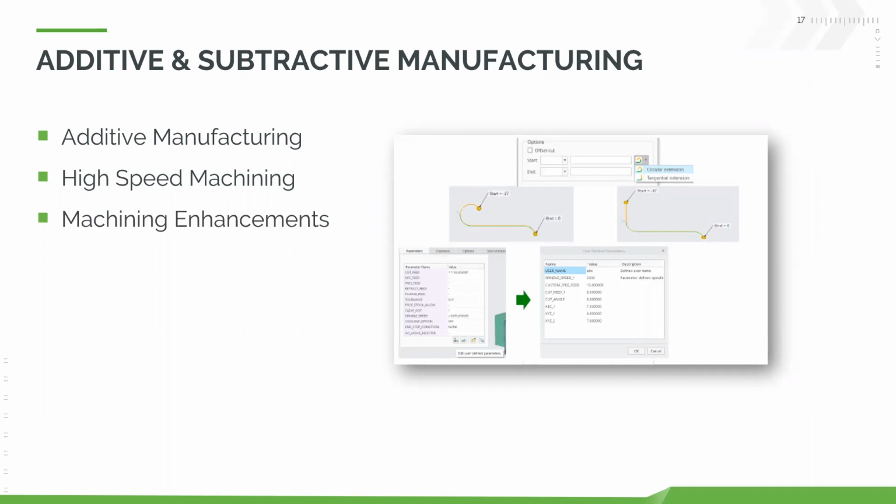You can now define your own, as many different CL commands as you want, and then add them into your toolpath. So really whatever your post-processor needs might be. And then finally, we added in cutter compensation support. This is within profile passes in high-speed milling roughing. This was a customer request that we got to get cutter compensation in there. So definitely a nice to have in that sense.